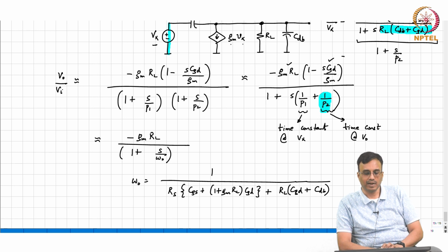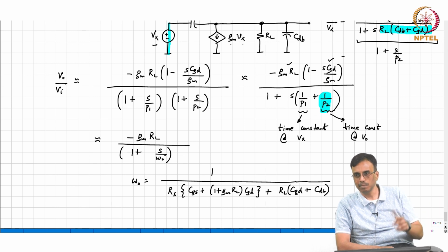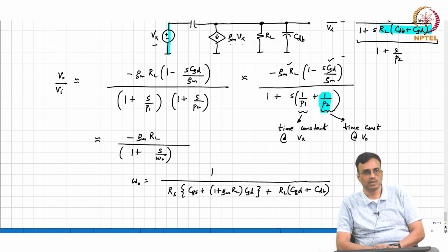The effective bandwidth is the reciprocal of the sum of the time constants. The bandwidth is simply inversely proportional to the sum of all the time constants you find everywhere, so to first order, the bandwidth of the system is simply 1 over (tau 1 plus tau 2), where tau 1 and tau 2 are the time constants.